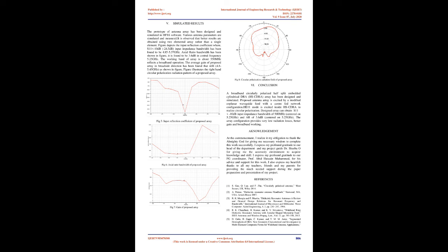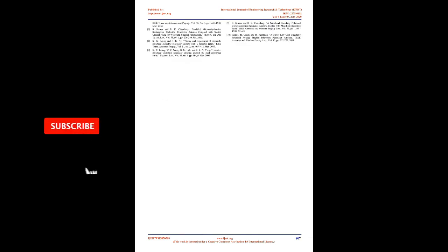B. Effect of slotted patch. Fig. 4 shows the effect of slotted patch on input reflection coefficient and working bandwidth. A single DRA structure exhibits higher reflection losses than an embedded structure. The working band is enhanced from 300 MHz to 550 MHz by the insertion of the slotted patch, so the proposed antenna exhibits broadband operation. Axial ratio and radiation pattern reflect the generation of right-hand circular polarization due to the slotted patch on the left side of the embedded DRA. Input reflection coefficient, unslotted patch. Radiation pattern, unslotted patch.